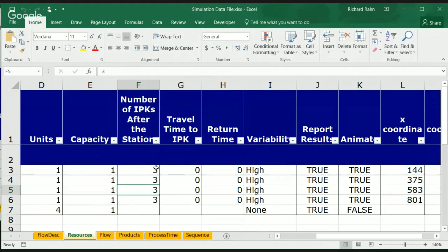I could virtually guarantee you that by adding more, it's not going to show any improvement. Can we reduce this variability? That sounds good, and that's kind of like the level loading philosophy, right? Make sure the work is standardized, training, all those things, and we could go from a high to maybe a medium. Yes, that's worth doing, but again, keep in mind in a true mixed model environment, there are limitations to how much you can actually accomplish there, because you're going to have some variability that's not really in your control. It's the variability of the different products, right, and the different work content coming down there.